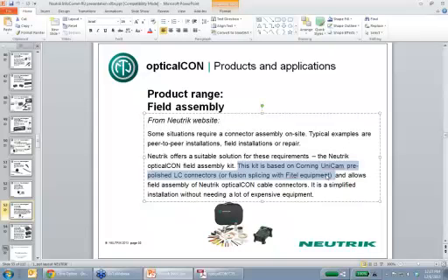This could be a little controversial, but there are three basic ways in which fiber optic connectors are typically terminated. One is an epoxy and polish process. This is the military mil-spec process. It's what BTX does. It's what everyone else does who terminate opticalCON. It is the best way to go. You apply some glue, you stick the ferrule on, then you have a lot of polishing, a lot of testing, repolishing, and it provides the strongest connection with the lowest attenuation. We always want low attenuation.